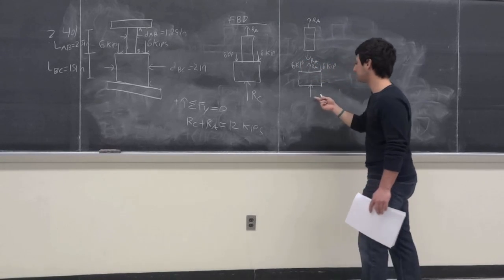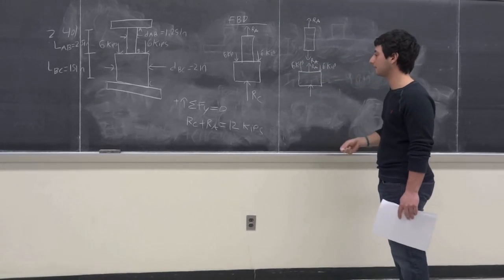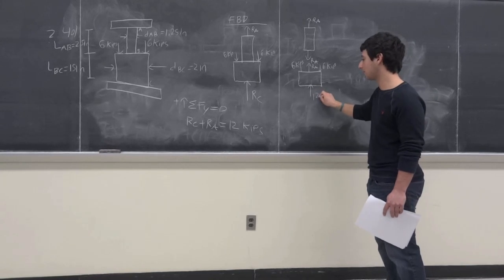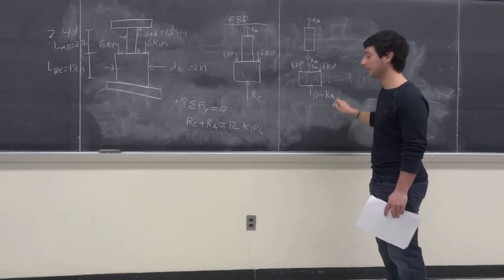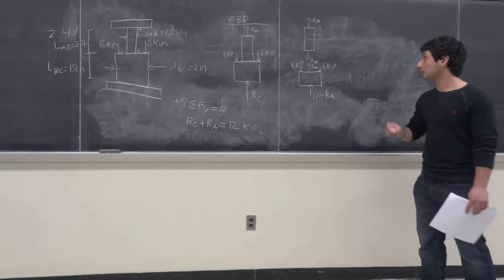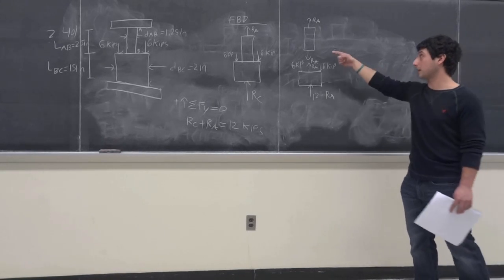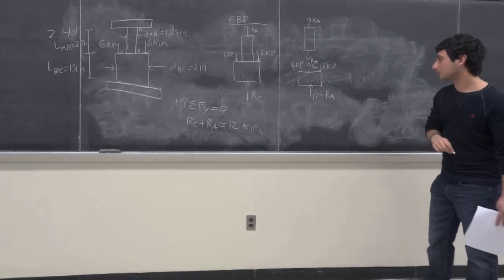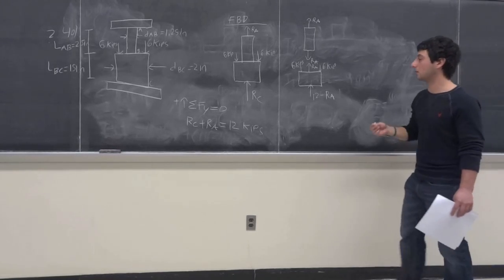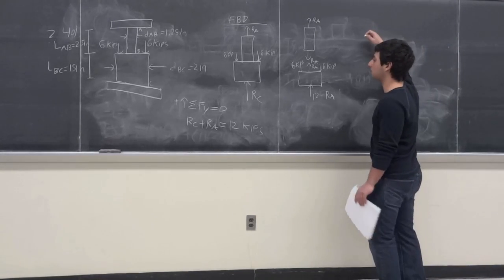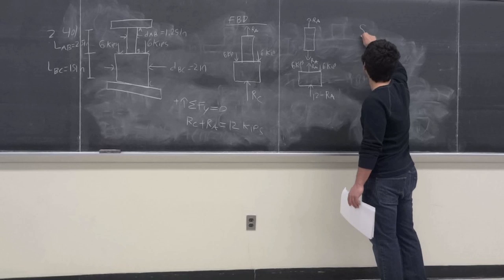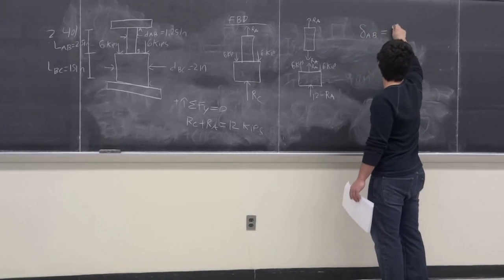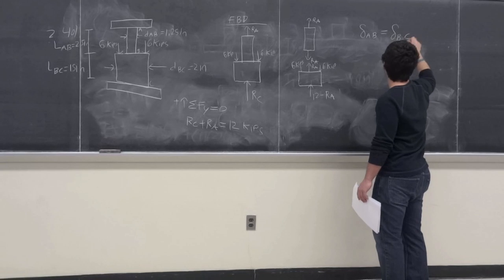All right, so what is this? What is this on the bottom? It's RC, but what is that? This is 12 minus RA, right? You guys see that? All right, so these are the individual free body diagrams. This is rod AB and this is rod BC. Okay? All right, so from mechanics of materials, we know that delta AB has to equal delta BC, right?